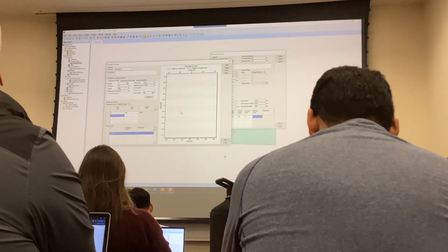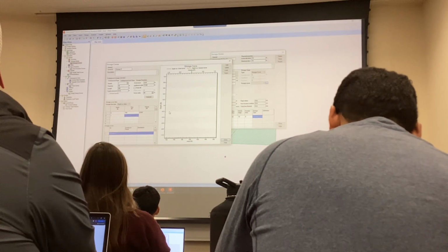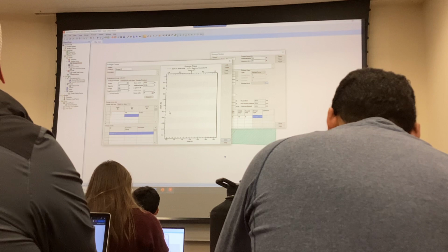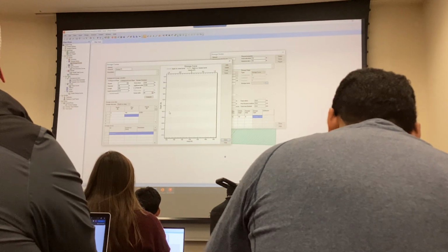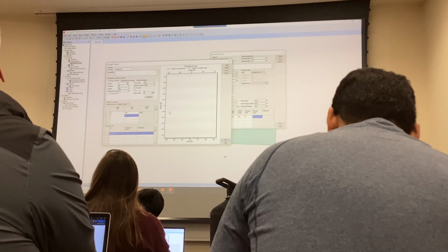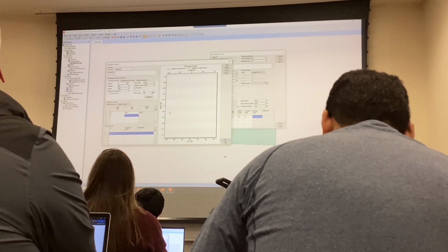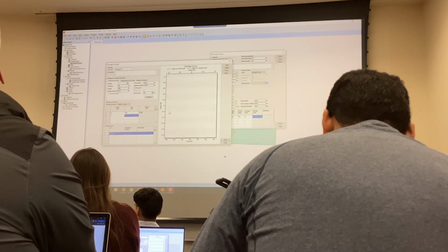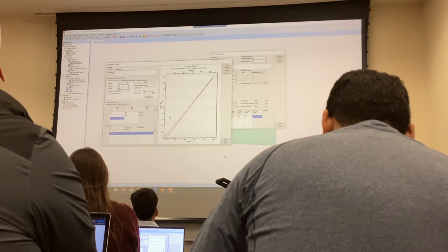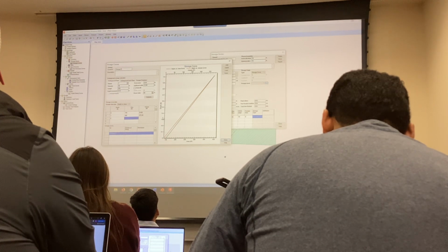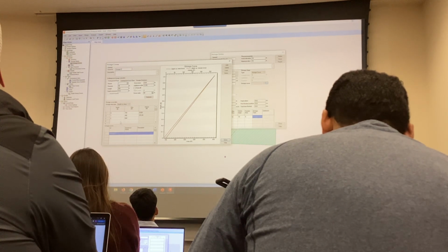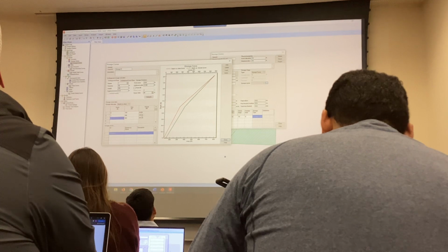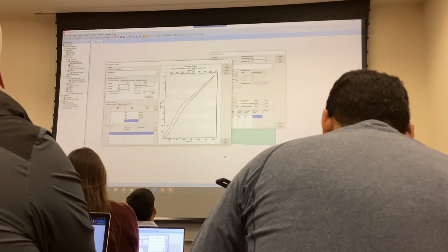Okay? So once you're done, you put the next depth. It doesn't need to be an increment of 1. It can be an increment of 0.5, or whatever. So you go to the next one and do the same thing. Since you already have the contour, as we imagine this area, it looks like this area is going to be bigger than that area, right? So you can put a different area, let's say 400. And then at depth 2, you're going to have an increase, let's say double that, 800. And then at depth 3, you have 1500.